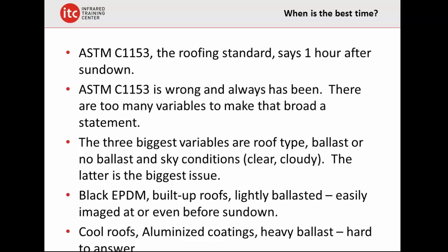Yeah. It makes sense though. Think about the heavy ballasted roof. If you have 6 inches of river rock and you go up there on an overcast day, do you think that river rock is giving up that heat? You're going to go up there and say, no, there aren't any roof leaks. And meanwhile, it's raining inside the building, and there goes your credibility.